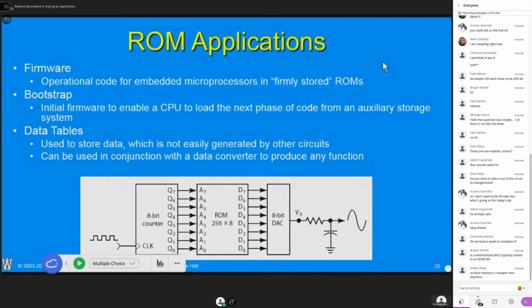Again, data tables. I often do this when programming older devices that are much slower and they can't generate the data in time. I use data tables, not necessarily in a ROM, but maybe in a software situation where it's just faster to do it that way, right? We have to make compromises somewhere. So again, you'll give up on space to hold this table because you don't necessarily have the speed to generate it, for example.